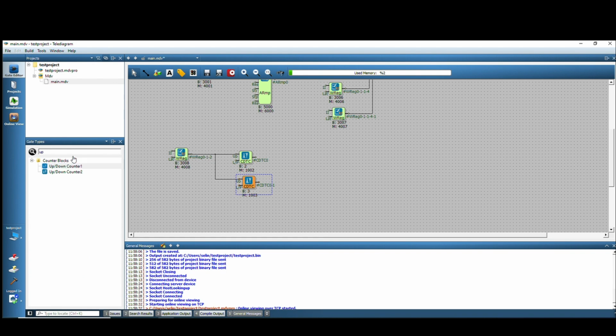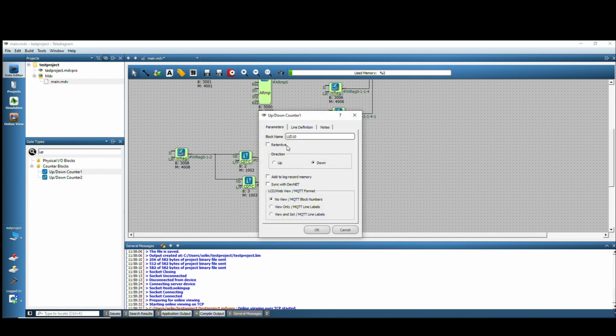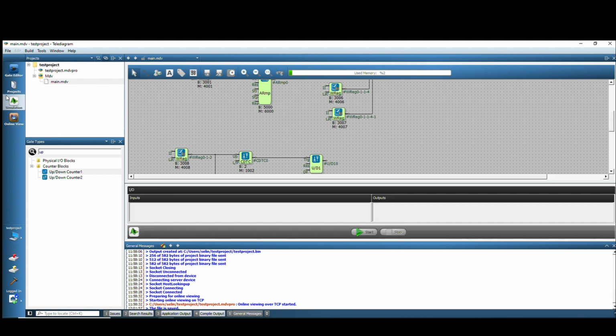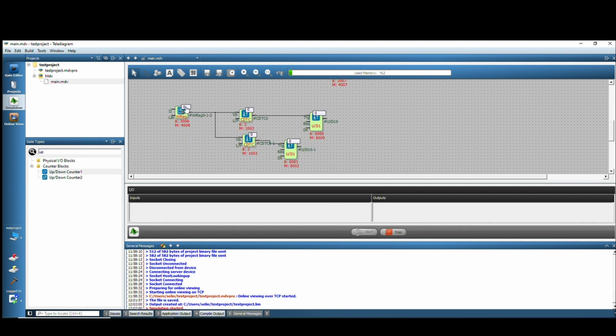With the up-down counter, we may not be able to instantly see the triggers sent in simulation. Therefore, by connecting the up-down counter block, we have the opportunity to observe whether it really generates. Now let's send a value. Currently, both triggers increased. Because a change of 5 occurred and a 50% difference occurred. Let's perform operations on this.